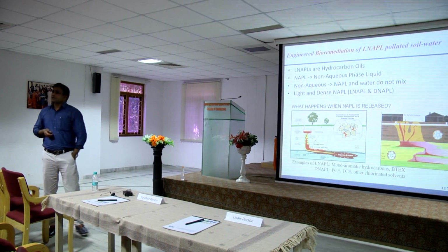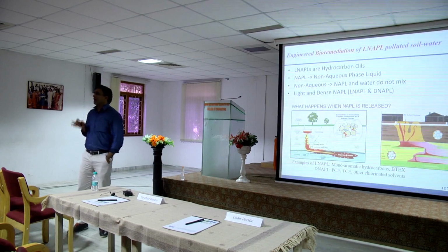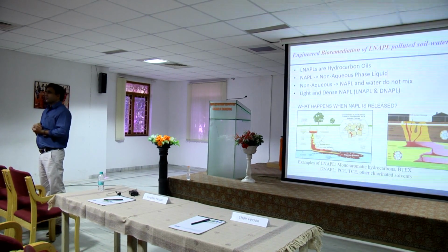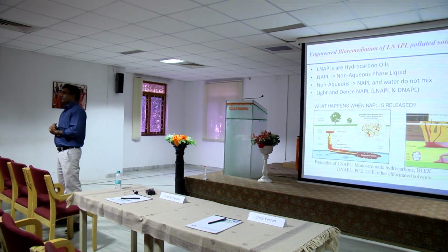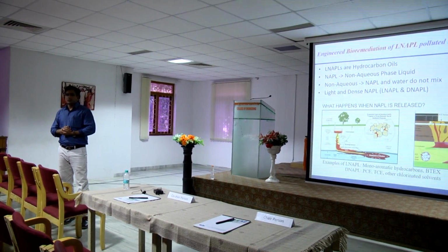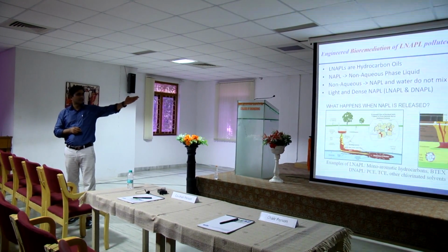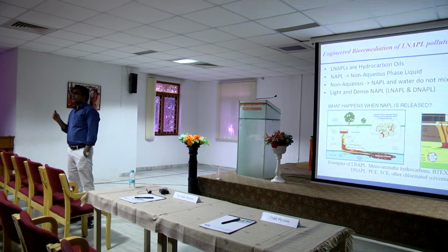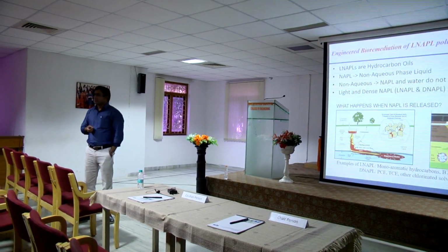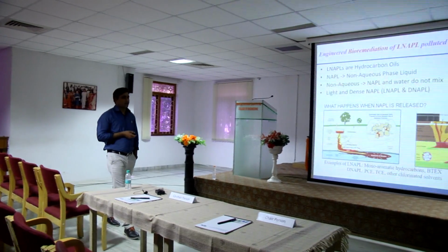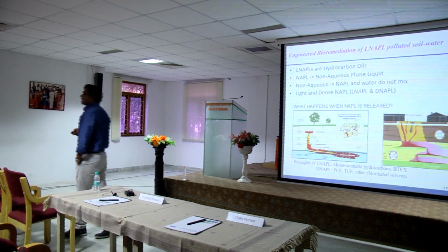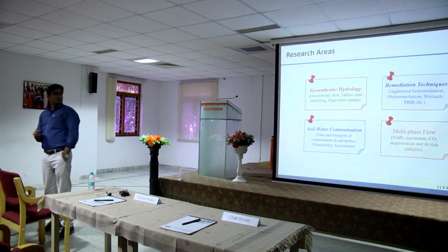Now, these hydrocarbon oils can be categorized into two types based on their density. If the density of these hydrocarbon oils is lighter than water, we call them light non-aqueous phase liquids, designated by LNAPL. If their density is higher than water, we call them DNAPLs. So NAPLs are categorized as light and dense non-aqueous phase liquids depending on the density.